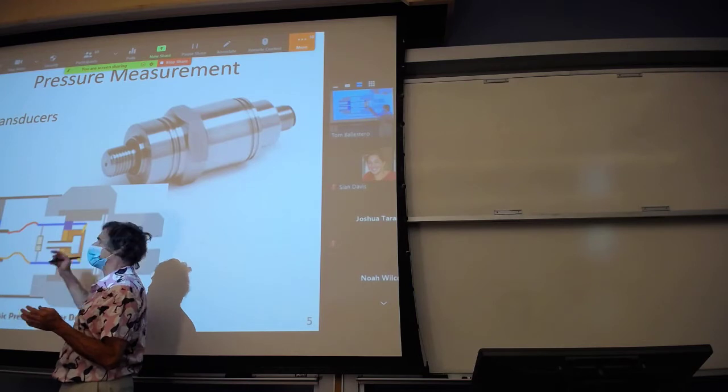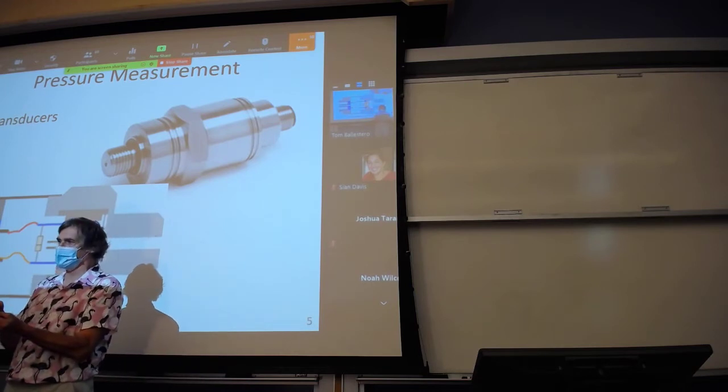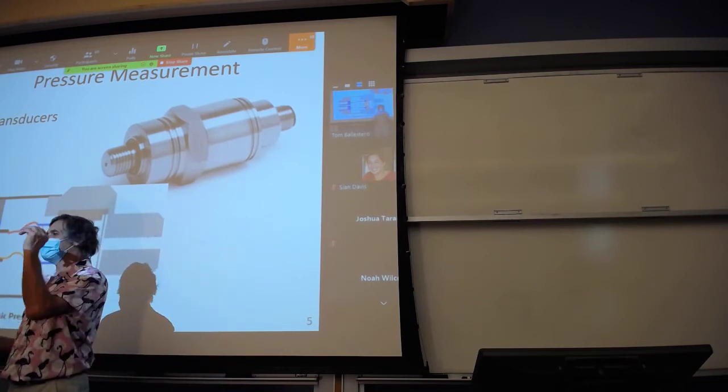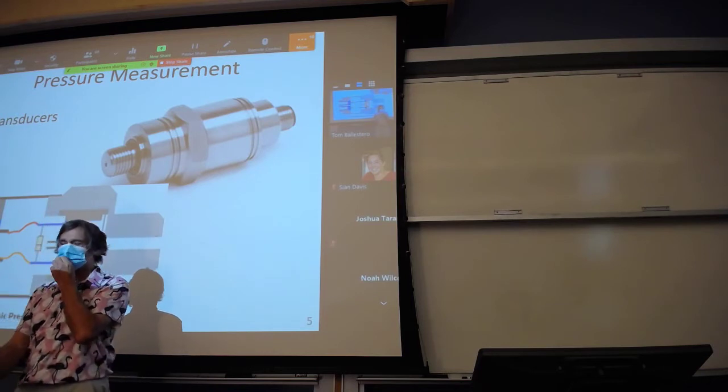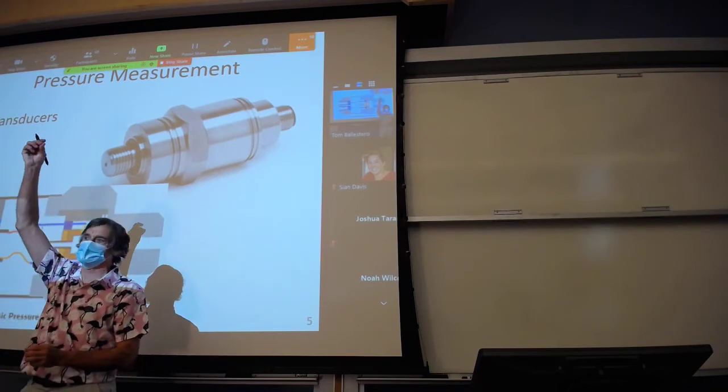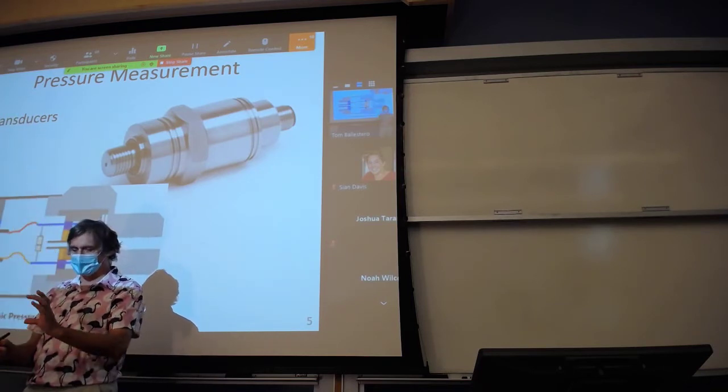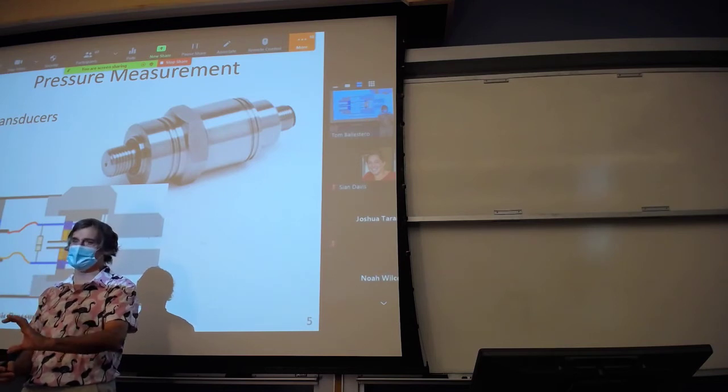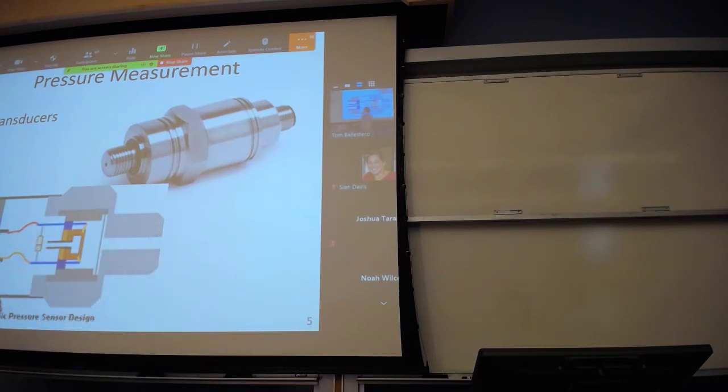So we will have a lot of these that read absolute pressure. Why? Because if we're putting them 300 feet down a well, we would need to run a vent line all the way to the surface. But instead, we'll have that one transducer down the well, and we'll take another one and plop it on the desk or on the ground right next to the well. So we measure atmospheric pressure, we measure the total pressure in the well, and then we subtract the atmosphere from the total absolute pressure, and that gives us the water column depth.